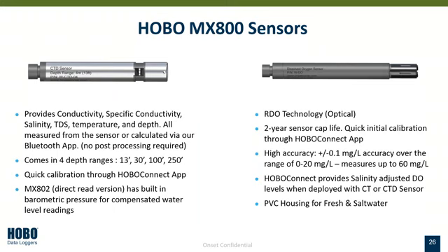We also allow you to do pre and post calibration readings. What that is, if you have some sort of meter, for example, that you don't necessarily want to calibrate with, but you want to take a reading at the beginning and a reading at the end, you can drop that in on the post deployment side through the app or through the software, and it will correct in a linear fashion. So as the data drifted over time, it will correct for that in a linear fashion and adjust your deployment.